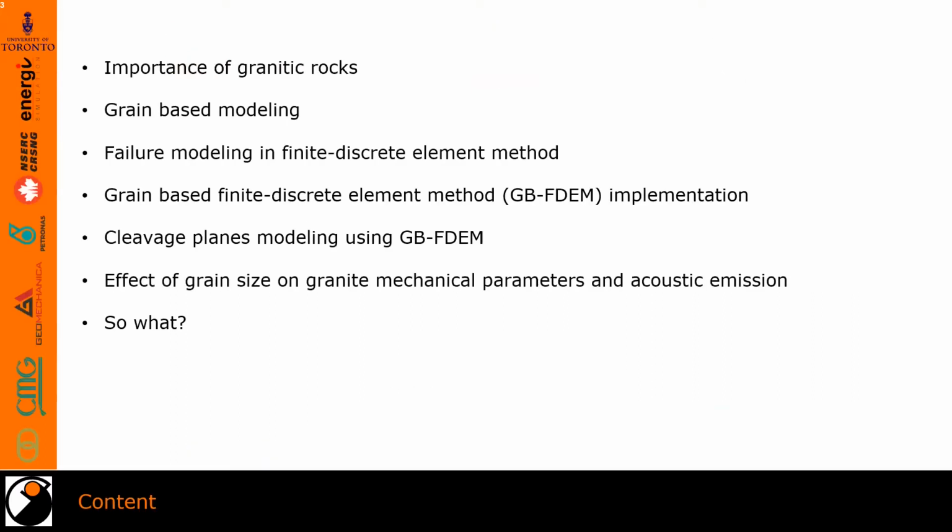I will start this presentation with an introduction of grain-based modeling capabilities in capturing rock microstructure and explain microfracturing modeling in FDEM. Then I will present two research showcases of implementing grain-based finite discrete element method to simulate cleavage planes during triaxial tests of granites and to investigate the grain size distribution effect on the mechanical parameters and the acoustic emission in granitic rocks. Then I will end my presentation with the conclusions and potential benefits of this study.